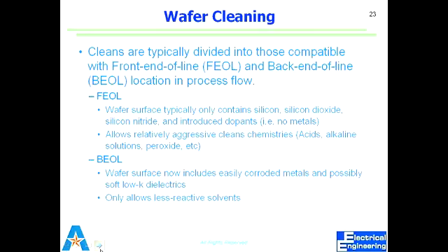So now, going back to the standards, how do we clean wafers? Every cleaning step would require your understanding of what is already there on the substrate. If there are many layers of devices that have been made, we may not be able to do certain cleaning steps because they can destroy those devices that have been made before. So those are divided into what we call FEOL and BEOL locations during the process. Front end is where we have nothing, we just have simple silicon or maybe silicon dioxide. We don't have too many layers made up yet, not too many metals deposited. It's called front end of line.